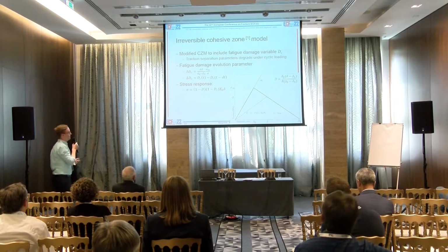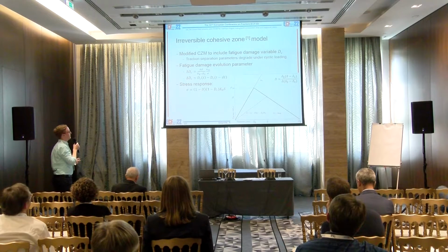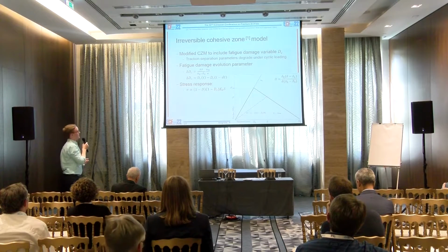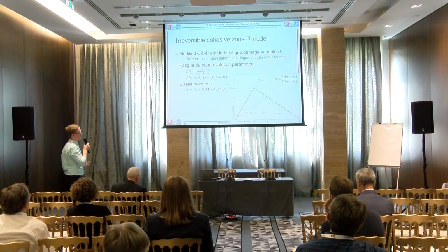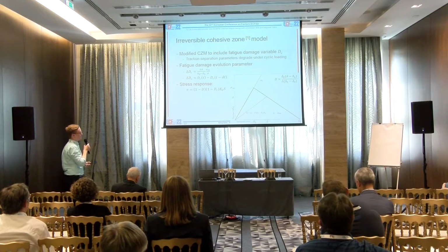Therefore, the stress response in the element is now degraded from the monotonic case and the fatigue case. Even if there's no monotonic damage occurring, the stress is still degraded due to D_c. You can see this in the way the element stiffness has been changed.